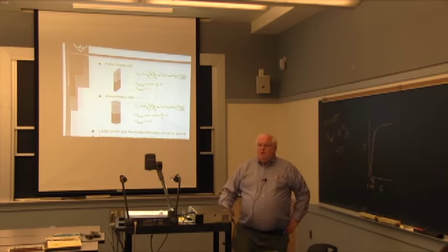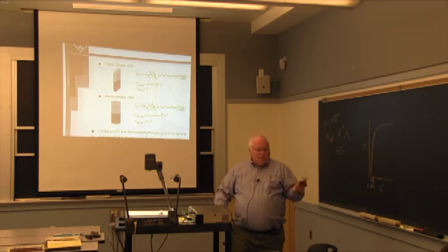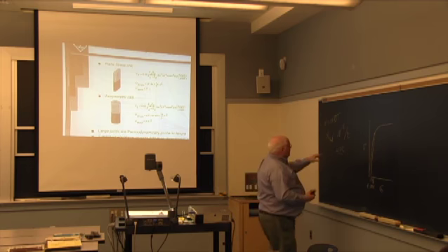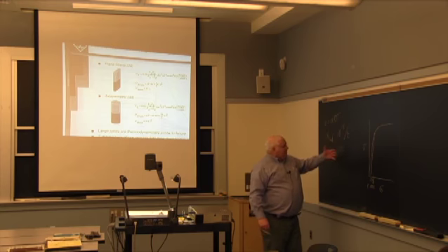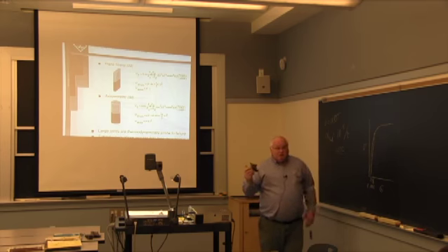Now, when we do dissimilar material bonding, and here's a turbine blade, which they put a ceramic coating on here. The problem in general with metals and ceramics is they vary by about an order of magnitude in the thermal expansion coefficient. A ceramic has something on the order of maybe 2 times 10 to the minus 6. 5 times less. Okay, so maybe it's 400 degrees centigrade or 600 degrees centigrade. You still have some pretty serious problems.